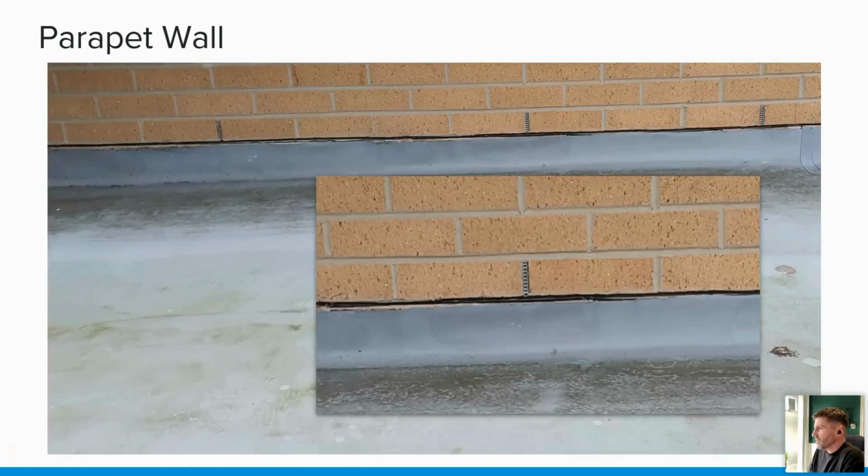So we've done weep holes, we've had a look at this. This is the same detail as before, so we know what weep holes look like. They don't always have this plastic weep hole kind of thing in there. Sometimes it's just a hole in the perp end of the brickwork. Sometimes it's sealed down to here, and there's just like a little plastic tube, for the want of a better description. But it's always worth looking at this, not only on the inside of the building as well. If you can see on the outside of the building, if you can look up and see the face and see if there's any kind of evidence of water running down the outside at these kinds of levels as well, then that will say that you've got cavity trays in there as well. Important.